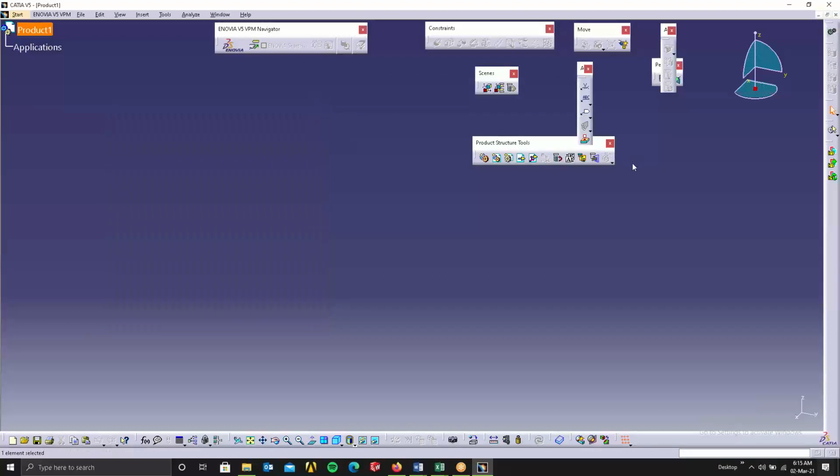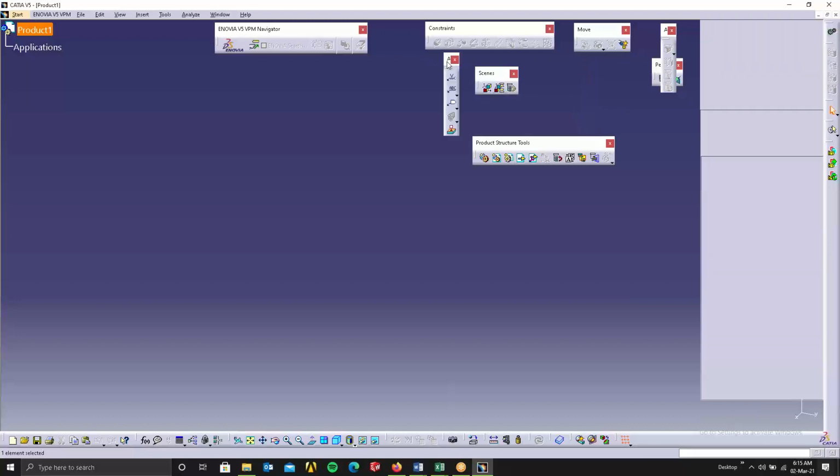And in trimetric, you can use different angles on both sides, so that the angles are not equal to each other. And these different views are used when you want to make sure that all the lines are visible. If you just want to represent them, I'll just explain that again.